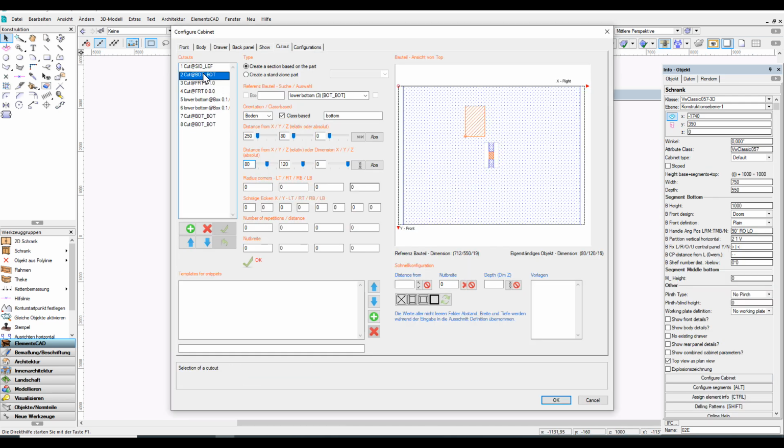But you're not only limited to cutouts, you can make some kind of lifting hole as well. This is an example. I go back to 0 radius, and I make a distance here with 200, so I have a better distance here. And this is my cutout, and I duplicate this cutout, and now I want to make a thickness, let's say 5 millimeters everywhere.